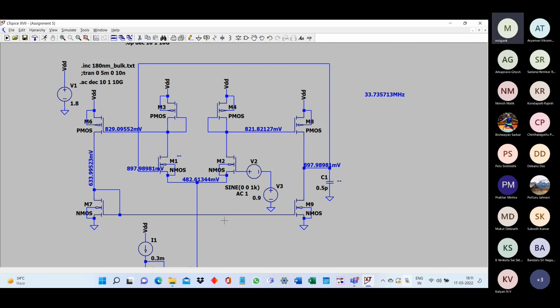Some people also put an inductor, a big inductor in the feedback rather than R. What will happen? Inductor omega L is the impedance, and therefore at omega equal to 0, impedance is 0. It will be shorting. So from a DC point of view, whatever is the output voltage, the same will be the input voltage. But if you talk about the high frequency response, mid values response, there the omega L impedance will be much higher. It will be open circuit, so you can ignore it. So if you put a very large L, that is also valid. Some people do that also. But again, you may find some artifacts because of the artificially introduced L that we have to be careful about.